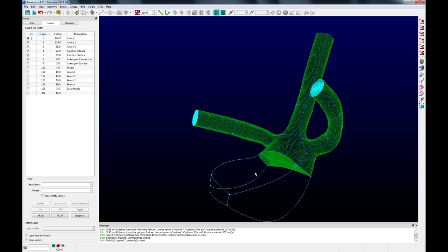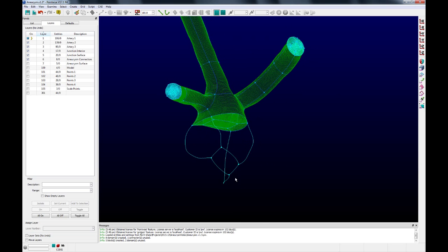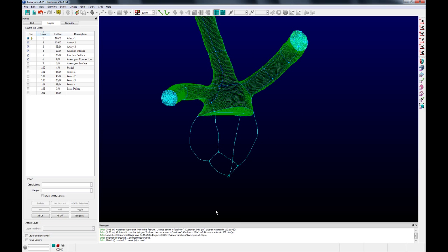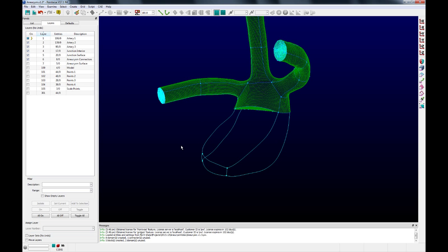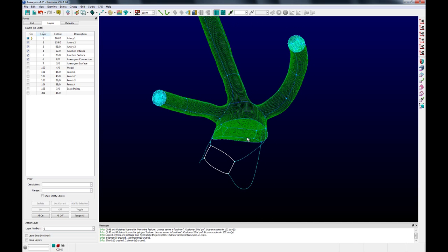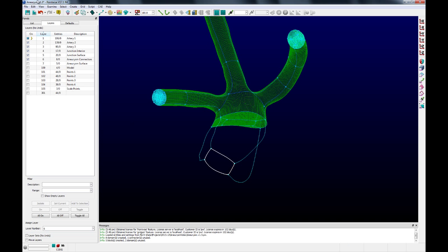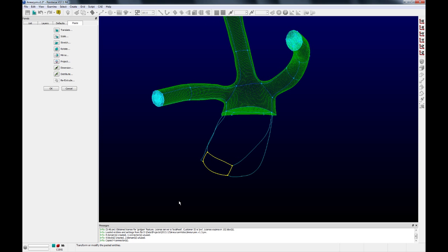So I'm going to turn on the connectors. Again, I've already run the smoother on these and projected them so they're conformal with the database. But what we need to do is define that inner topology, that tip block and everything that I was talking about at the very beginning. So to do that, we're going to turn our selection mask over to connectors. We're going to highlight this bottom topology here, which is topologically consistent with this H block up here. We're then going to copy and paste this selection, and we're going to use this to create that upper portion of the tip block that I talked about earlier.